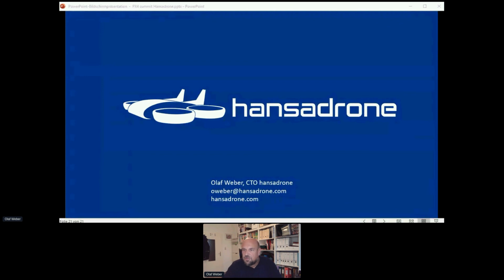Another question from Jeff. Any testing done in direct sunlight with a light at sunset? That's a good question, actually. It is causing problems, yes. For now, we're using a red light on the drone. And if there's direct sunlight or sunset sunlight, this is causing problems. So one idea that we came up with is using a coded light signal. You could use your light like a Morse code or something, and recognize that code sequence to identify the actual drone light, but this is still in development.